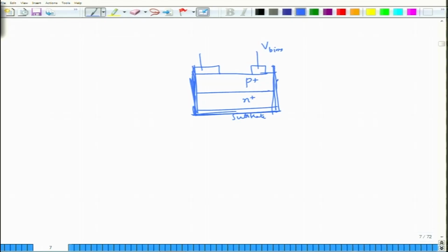Okay. So, this is how it would be, and there would usually be a small layer of anti-reflection coating, and light would come in from this side. So, you would illuminate from the top, so that the light would actually propagate through and create an electron and hole pair. Now, this region would normally be the depletion region, and because of heavy doping on both sides, the depletion region is quite wide. Okay. The width of the depletion region is W, or we will call this W_j. J stands for the junction.